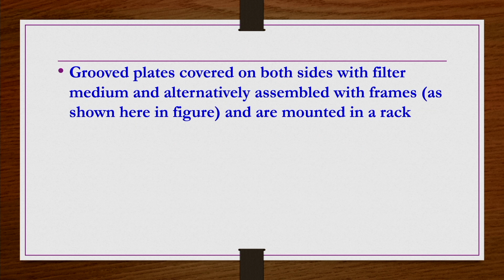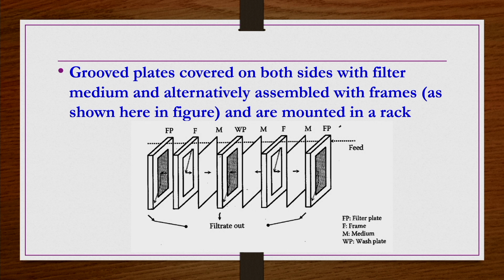So, grooved plates in general are covered on both sides with a filter medium, because the filtrate comes through the grooved plate only, and they are alternatively assembled with frames as shown in the picture, as I already mentioned, and mounted in a rack like this. Okay.